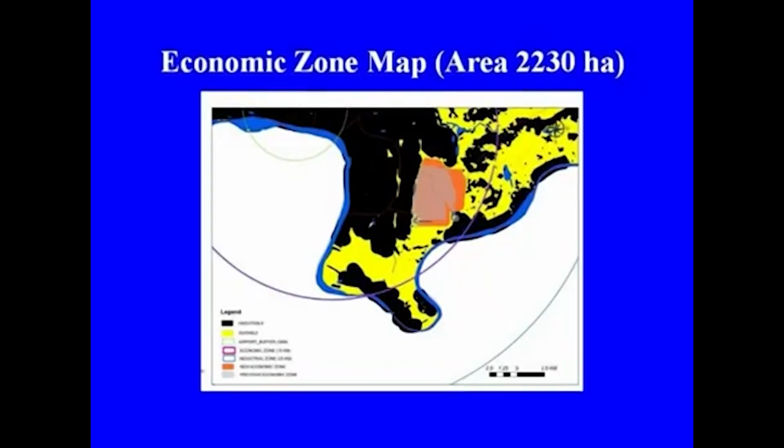So, when we go for identifying the economic developmental activities, there are certain minimum criteria to be maintained, and that is that the economic developmental areas must have a minimum area between 1500 to 2000 hectares of land. There should be proximity to roads, and thereby we have created a buffer of 100 meters, that is, the economic zone should be so located that it should be within 100 meters of the existing road, and also proximity to the tourist places which are there.